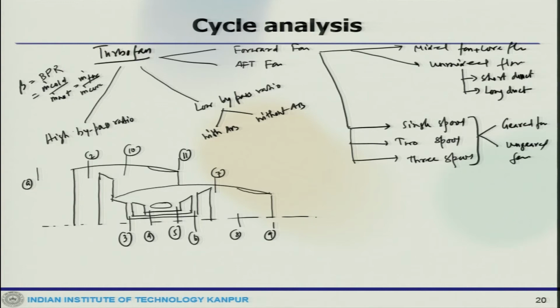So, this is a double spool layout, a double spool system where the fan plus LPC are driven by the LPT, and the HPC is driven by the HPT.